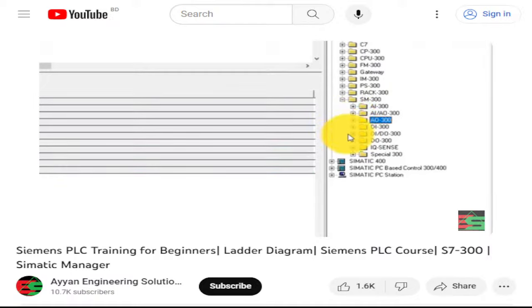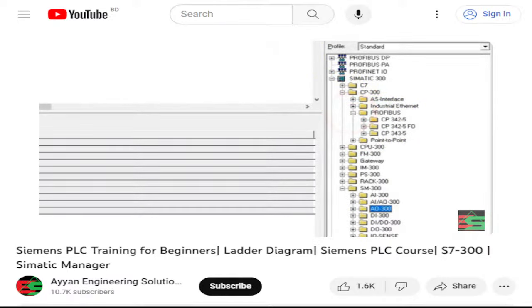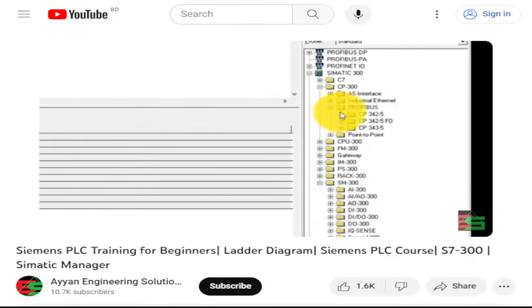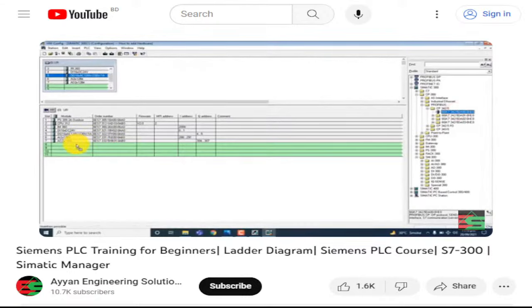So by using this table, you can program your PLC by Profibus using this addressing of input and output module, analog and communication module. If you have any question regarding this lecture, you can raise a question. Okay. So this way you can add your hardware.